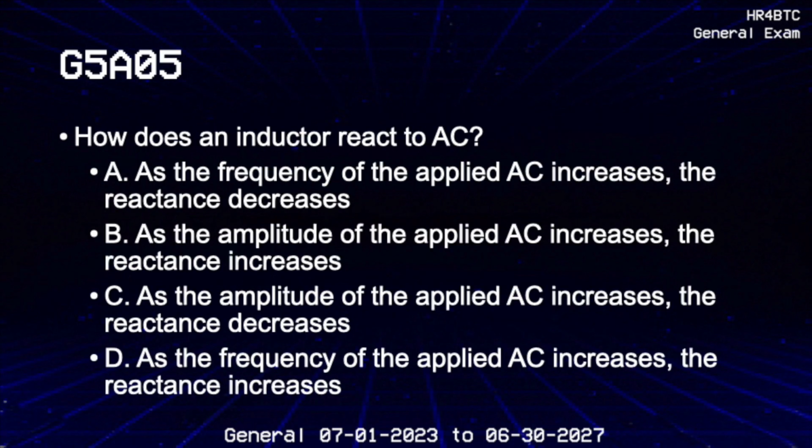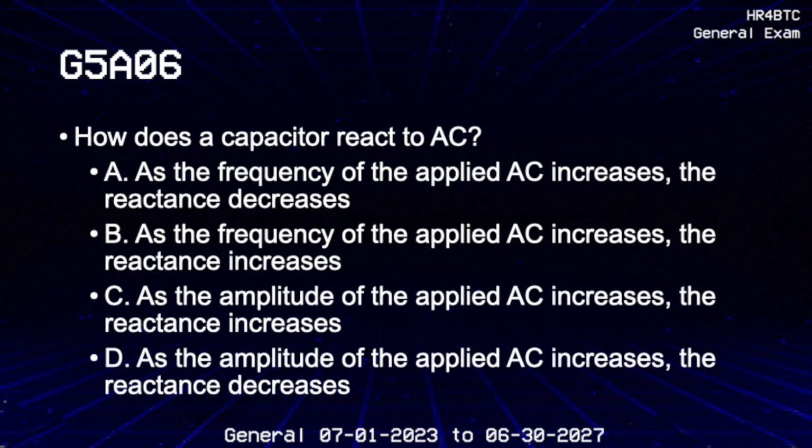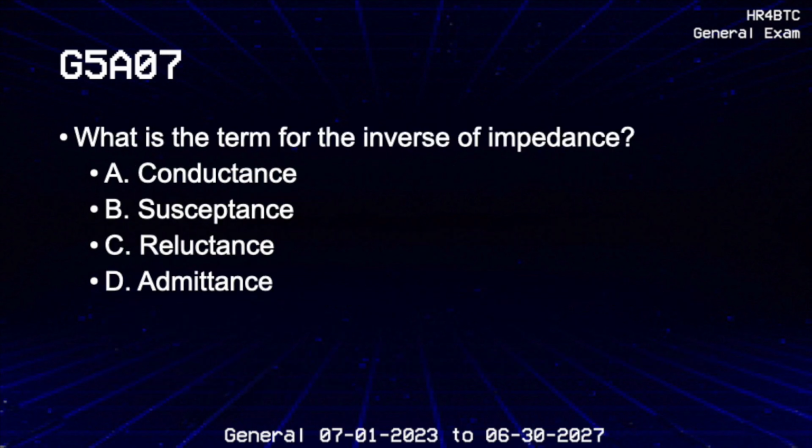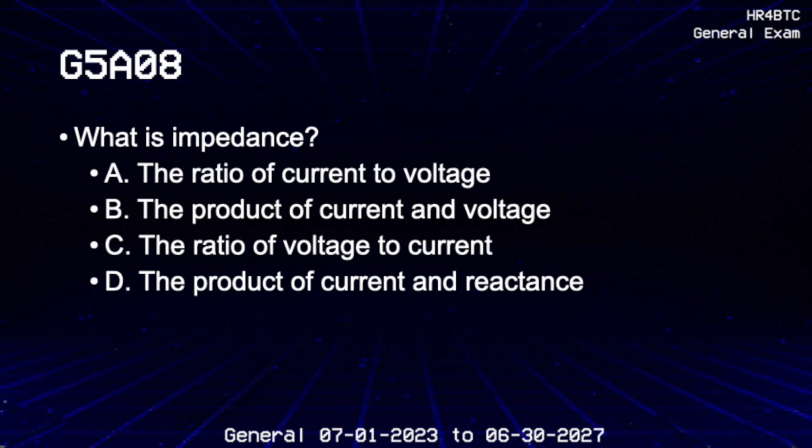How does an inductor react to AC? As the frequency of the applied AC increases, the reactance increases. How does a capacitor react to AC? As the frequency of the applied AC increases, the reactance decreases. What is the term for the inverse of impedance? Admittance. What is impedance? The ratio of voltage to current.